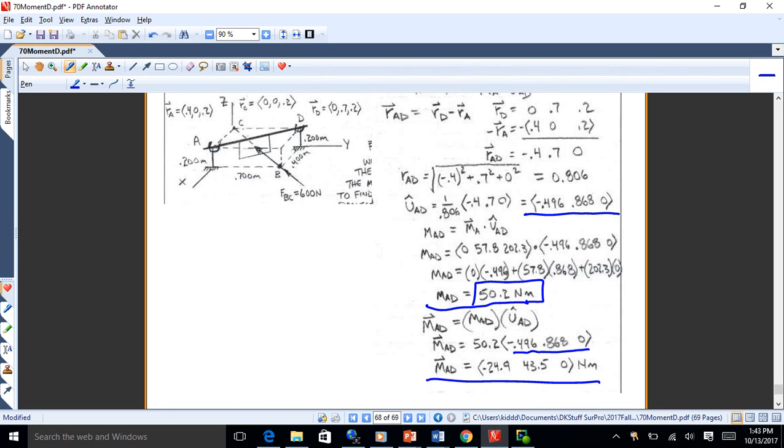All right, so find the moment vector first about a point on the object and then dot it with the unit vector for the axis. Got any questions on that? Okay. You said moment vector dot with unit vector? Right, with the unit vector along the axis. And I think if you look at the notes there, that little written paragraph on the upper right just basically describes what you need to do. And then the rest of it is just the calcs to actually do what that paragraph describes.